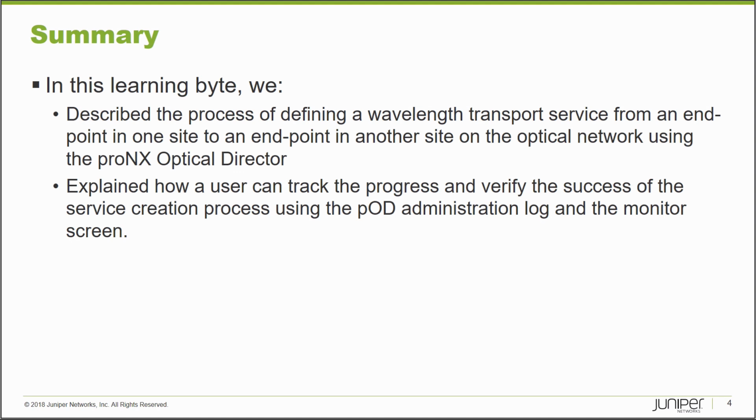To recap, in this learning byte, we described the process of defining a wavelength transport service from an endpoint in one site to an endpoint in another site on the optical network using the proNX Optical Director, and we explained how a user can track the progress and verify the success of the service creation process and of the resulting service using the POD administration log and the monitor screens.